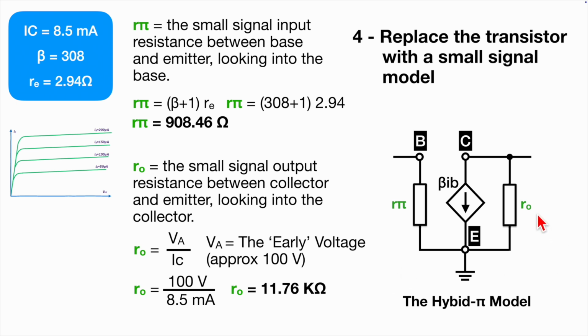really you need internally to that current source for it to have a very, very high impedance. Because if it has a lower impedance and you connect your circuit to it, then there's going to be more current flowing internally in the current source than there is in the circuit that you want a fixed current flowing through. So it's kind of the opposite problem. So that's why an ideal current source has an infinite impedance in parallel with it.